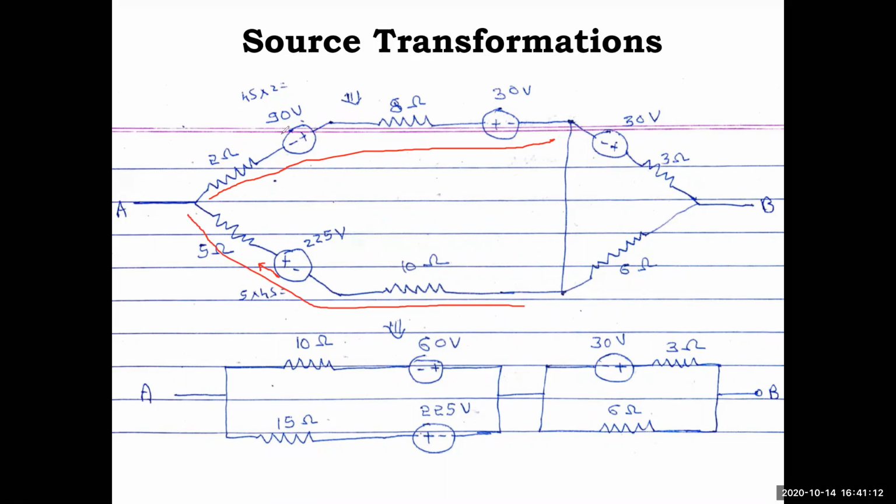Whatever is connected in series now, we can solve. Here 2 ohm resistor and 8 ohm resistor, so it is 10 ohm. That 10 ohm is written over here, and here minus plus 90 volt, and here plus minus 30 volt. Whichever is highest, 90 volt, that notation we write first, minus plus, and we subtract: 90 minus 30, 60 volt.